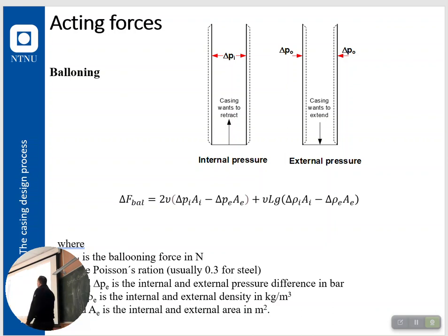And when you're pressure testing, expect also some stress to be going on in your casing. Why? Because you're pushing it out. And there's a relief part of it in the retracting. Now, if you have set the packer or if you have cemented this one, it is not free to move in the bottom, right? So it will transform into a stress.